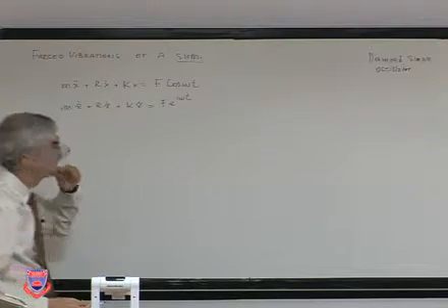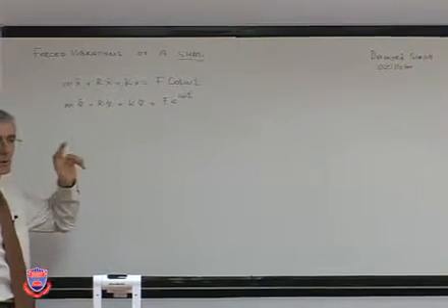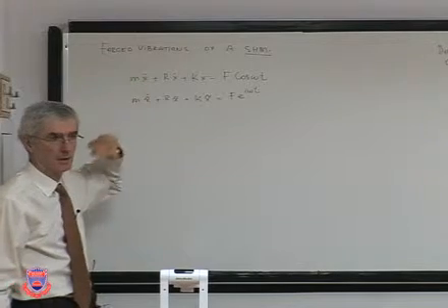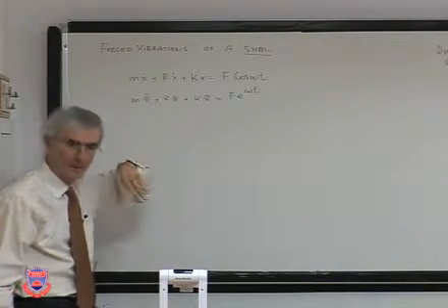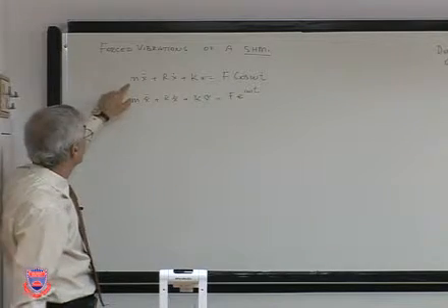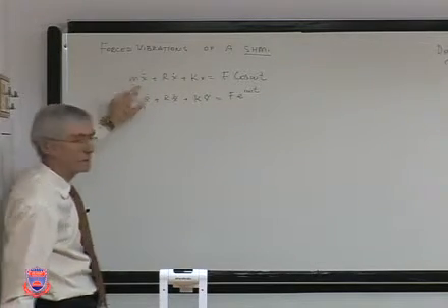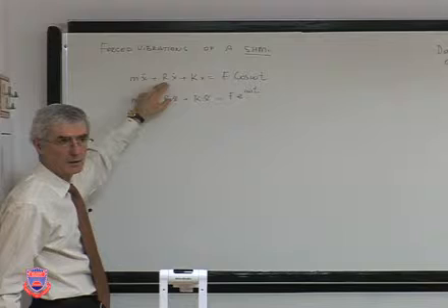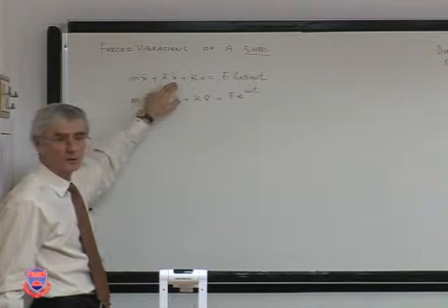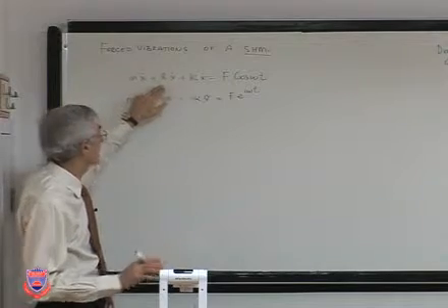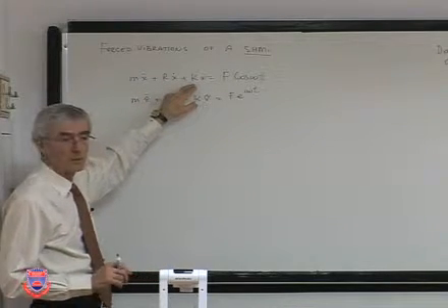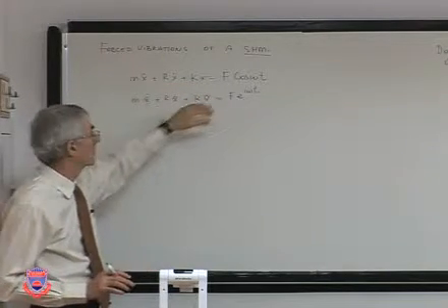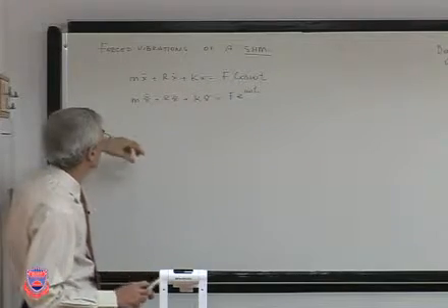Okay. Now, before we go, I just want to draw your attention to a couple of things. When you look at these terms, I know mechanical engineers probably know, and electrical engineers also in different terms. This is an inertial force. Mass times acceleration is just inertial force. And here is what we call a mechanical dissipation, but it's proportional to velocity. So the faster it is, the larger this force is. And this is the spring constant, proportional only to displacement. Okay, each one of them is a force term, so that right-hand side is also a force equation.